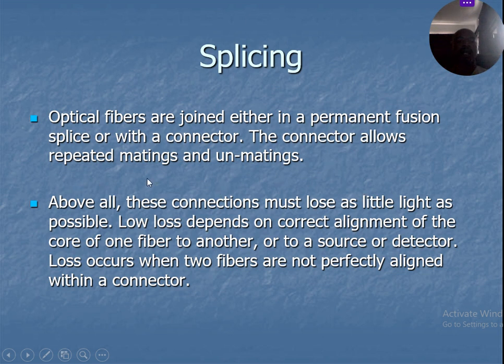The connectors allow repeated mating and unmating. So if you connect it well, it will mate properly, and then there will be low loss. And if you don't, there will be a lot of loss in the system. So as technicians or as administrators, you must be able to learn how to splice